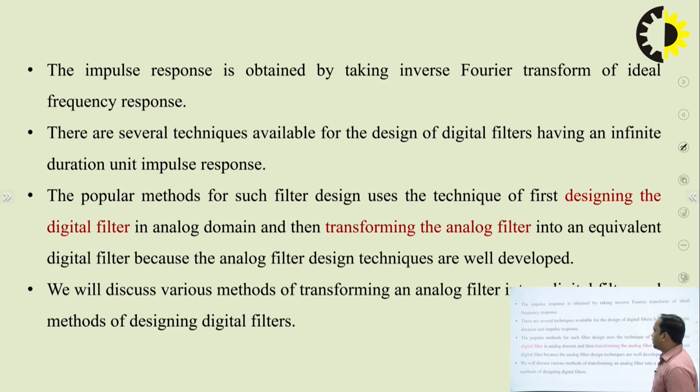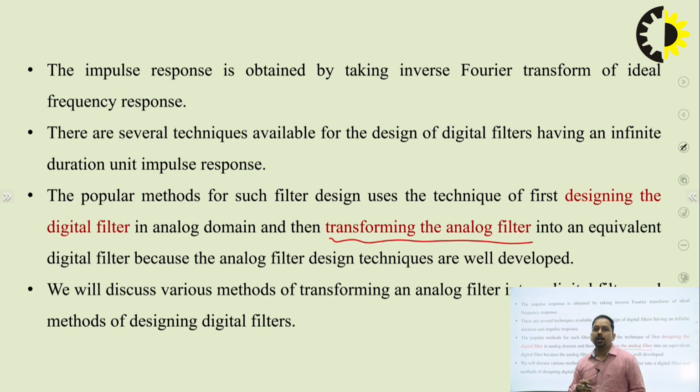IIR filters. The methodology behind designing a digital filter is, first of all, we design the filter in the analog domain, and after that we use some transformation techniques so that the analog domain filter can be converted into the corresponding digital domain.